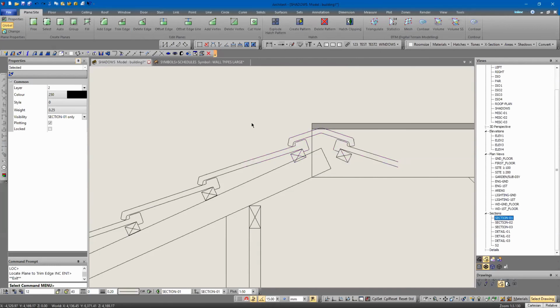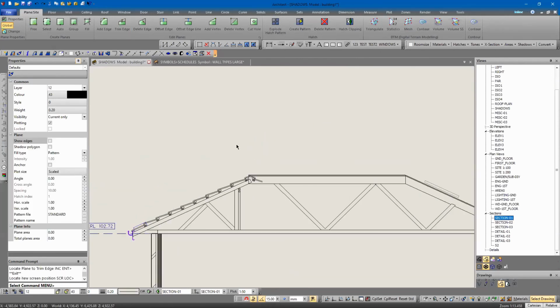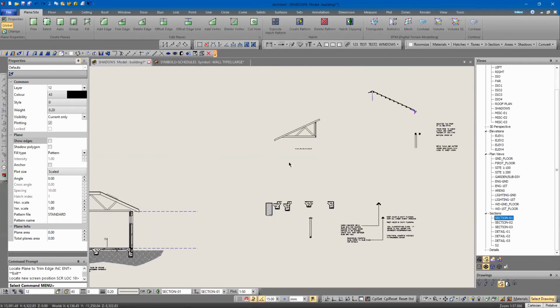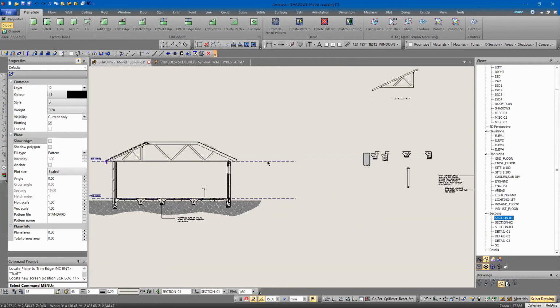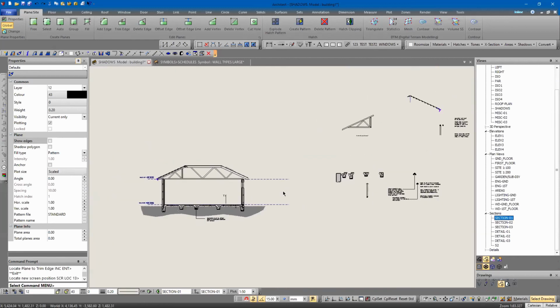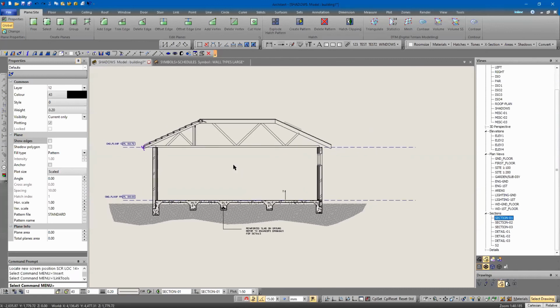You do a lot of unpacking. The only thing I'm worried about, if I do bring in and unpack, either unpack to a set or unpack. There's very few things I actually link in as live links, mainly because I want to keep them not live linked back to the database. Because then if I change something as a standard symbol and I come back to an old drawing, then it's changed and updated and not meant to have, and it doesn't give me a proper record of things.